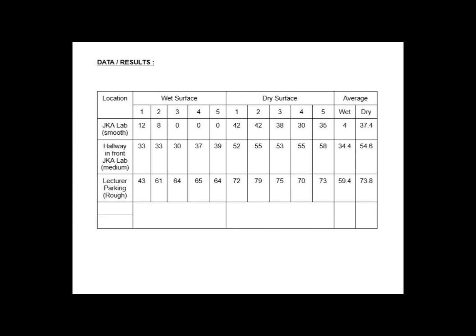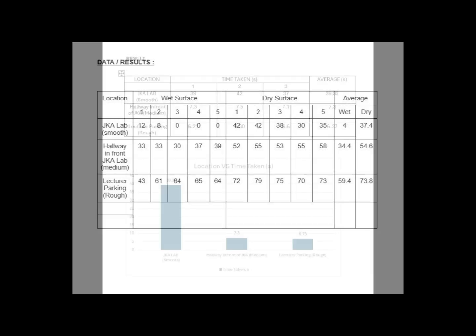And not only in the raining season where the road can be wet, it can also be due to oil spillage where the friction between the road and the tires gets reduced, then it can compromise the safety of the vehicles. So this test, the skid resistance test, is important to know whether a road's friction characteristics are safe enough for the vehicles to travel during critical conditions such as raining, where the condition is not favorable for the friction.